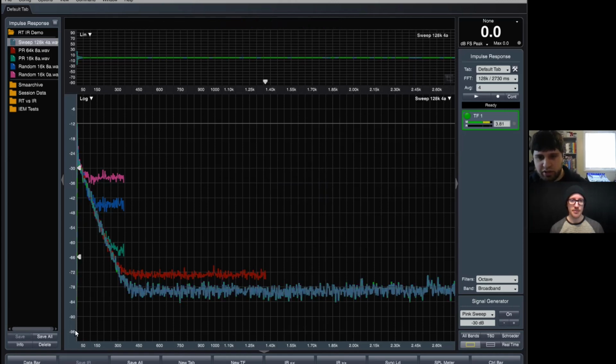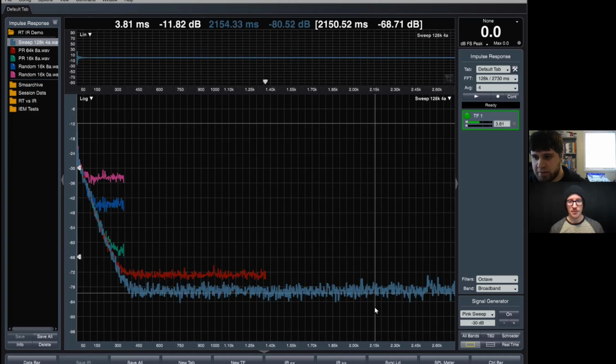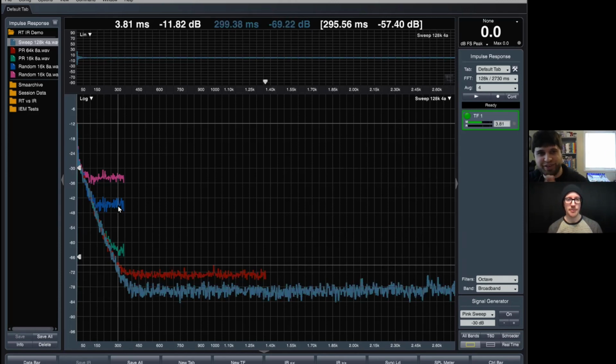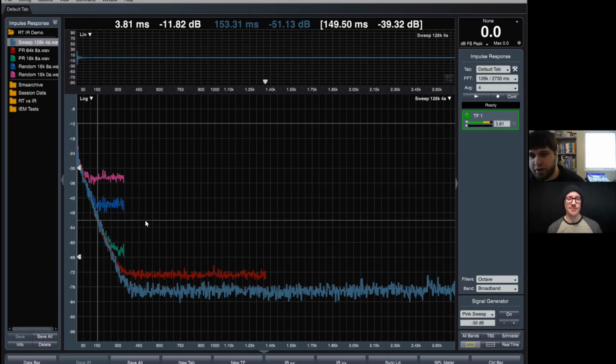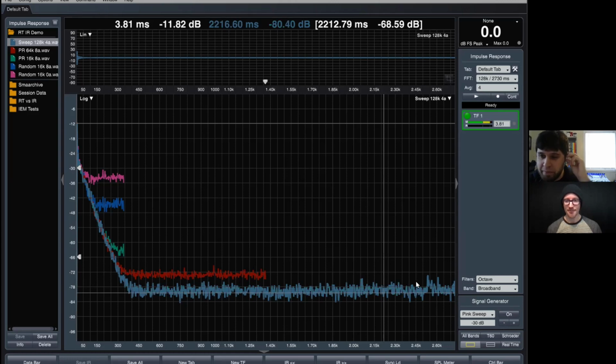And it's not super easy to see, but if you have a lot of THD in your system, these peaks that you're seeing here at the end, they're not super clear on this measurement, but those peaks are the separated out impulse responses of the additional distortion products. So you get an IR for your fundamental, which was the sweep tone that we hear, and then you get a separate IR peak for your second harmonic and a separate peak. Yeah, it's pretty neat.